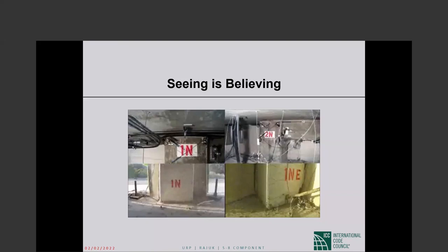So the load combination that says 1.2 dead plus 0.5 live plus 0.2 snow plus 1.0 E, in that load combination, E will be taken as rho times E sub H, which is the horizontal component multiplied by the redundancy factor, plus 0.2 S sub ds times D, which would be 20% of the short period spectral acceleration multiplied by the dead load.